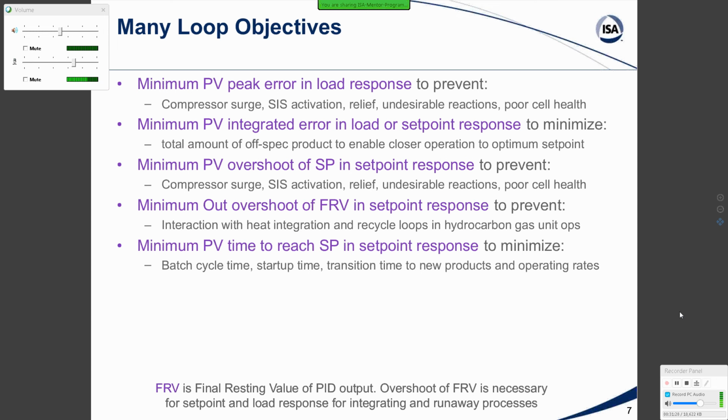And if I were to save 25 minutes on reaching set point, as they got to the initial operating point, or maybe as they changed it at some point in the batch, I saved 25 minutes, I could reduce the batch cycle time by 10%, and if the batch processing capability downstream could handle it, I increased the process capacity by 10%.